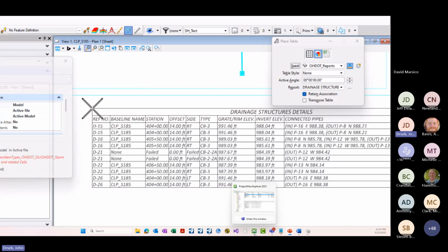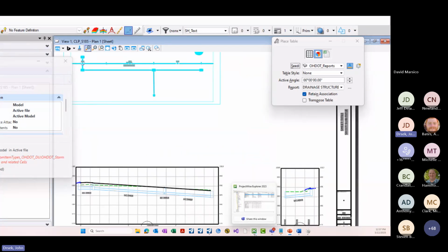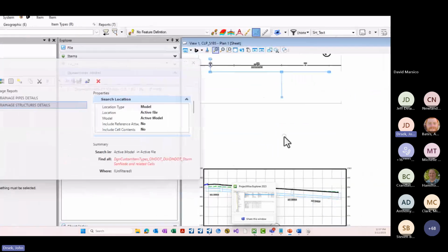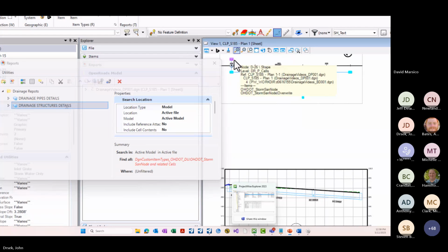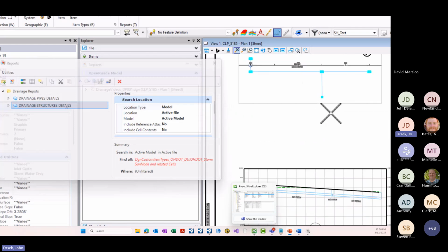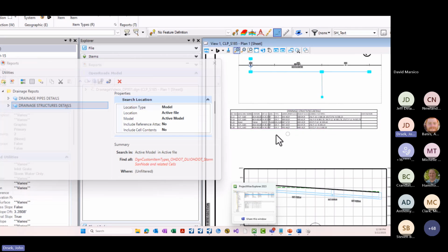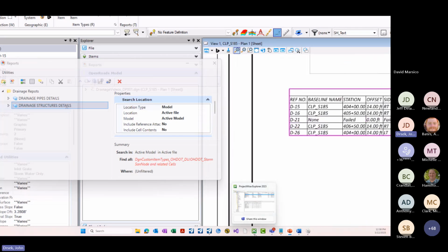This is a known defect with Bentley. The way I selected, it's picking up those nodes twice, so it is then placing them twice, which you don't want. But if I just go and select each one individually and place the table, it's not doubling them. So this is a defect. Bentley is aware of it and I think they plan on addressing it. It's just a nuance with nodes. I think it's the way nodes are placed. But just watch out that your table isn't doubled up.